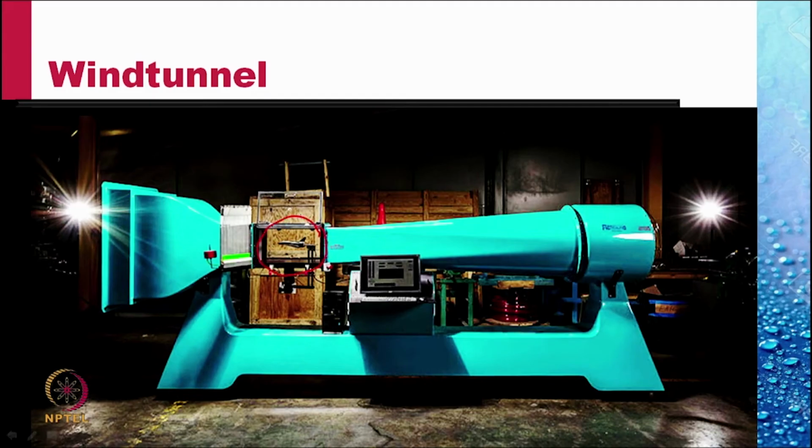we mount a model of the aircraft part that we want to test, and we create a flow in this channel. This flow is created by a fan in this portion which sucks air. The inlet of this tunnel is designed such that the flow that we obtain in the test section is uniform and straight.